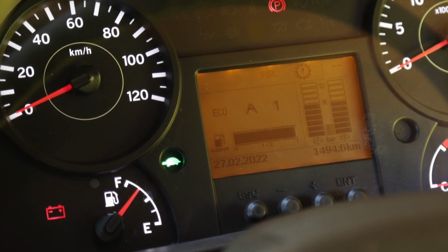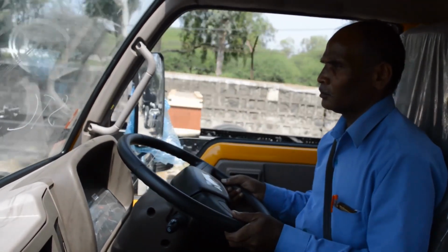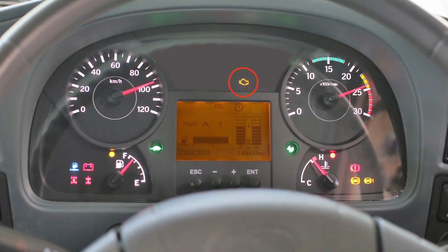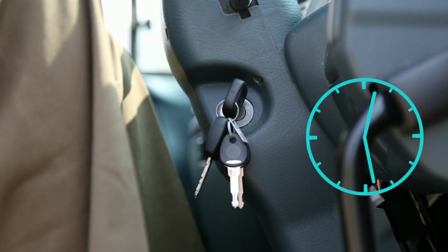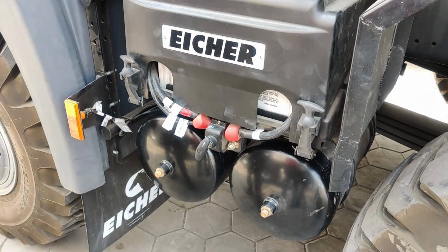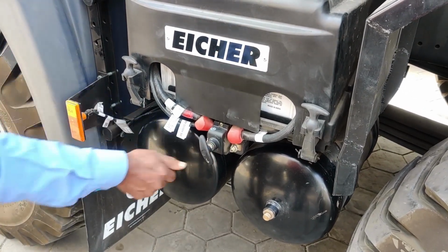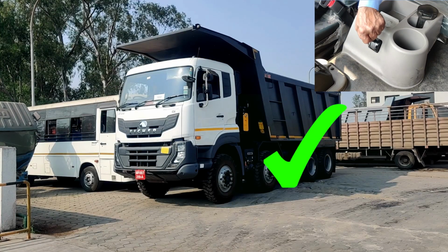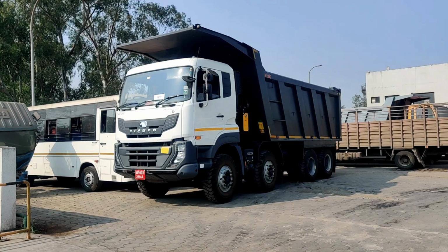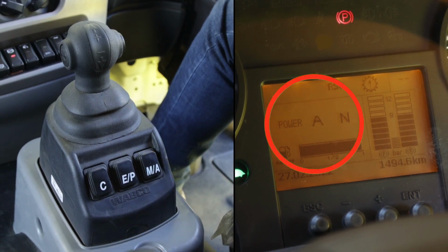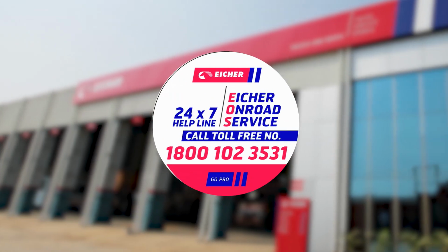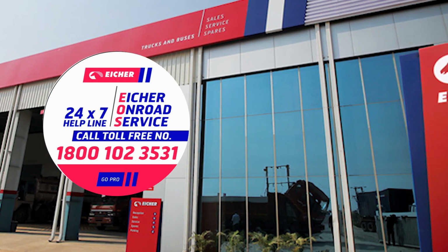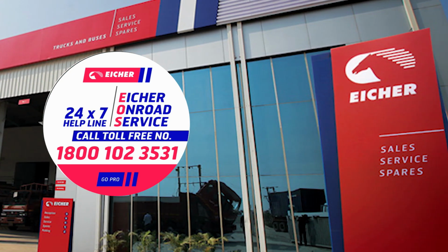Always drive in auto mode for better mileage and less driver effort. In case of any malfunction or error in the system, switch off the ignition and wait for a minute before starting again. If required, switch off and switch on the battery cutoff switch. Always use the parking brake to park the vehicle. Ensure the selected modes are displayed on the dashboard. In case of AMT malfunction, call Eicher on-road service or visit the nearest Eicher authorized service center.